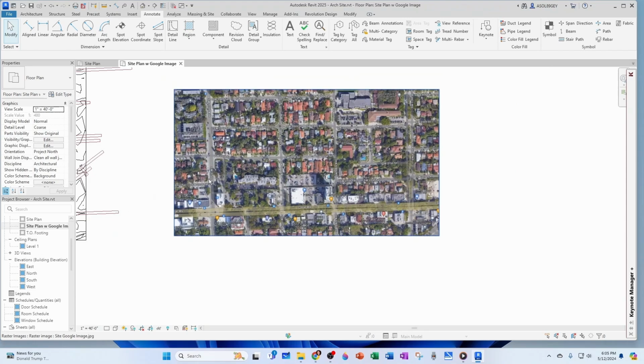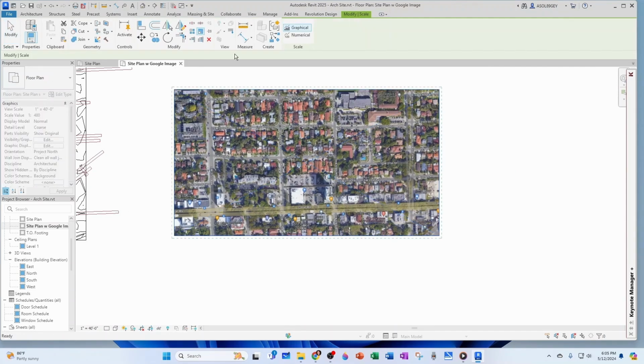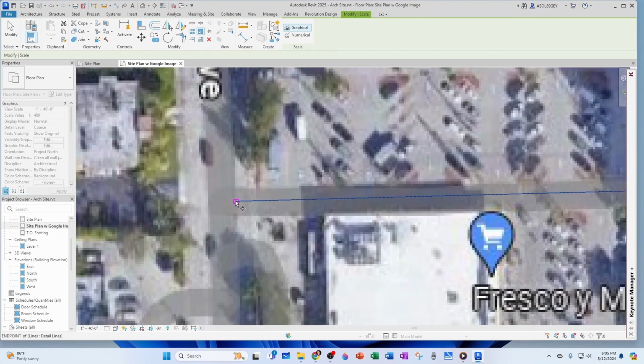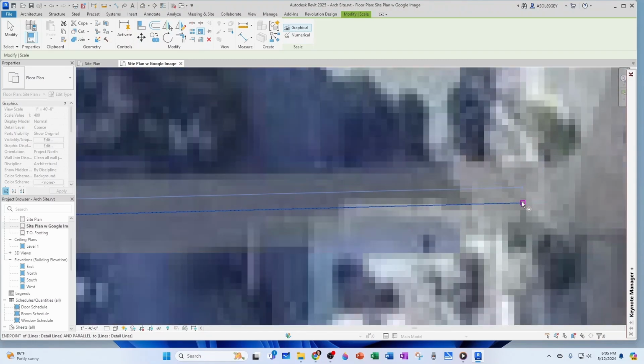And now you would click on your image, go to scale, select your reference point, which would be this one here, then select your other line, and then without moving anything, trying to remain in the same direction, you give it that size of 543.57 feet and hit enter.